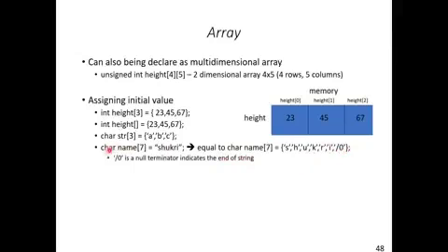What you see here, \0, is a null terminator to indicate the end of the string. If the name stops at I, you put it here so that it will inform the microcontroller that there are no more characters after the I, to indicate the end of that string.